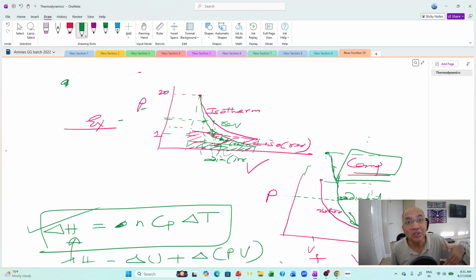Why? Because temperature increases, there is a heating effect. The more you compress, the more heating will happen. Temperature will be more, not due to any heat transfer. Q is not involved here. Work is involved here. So see, work is an equally important contributor to change in temperature.